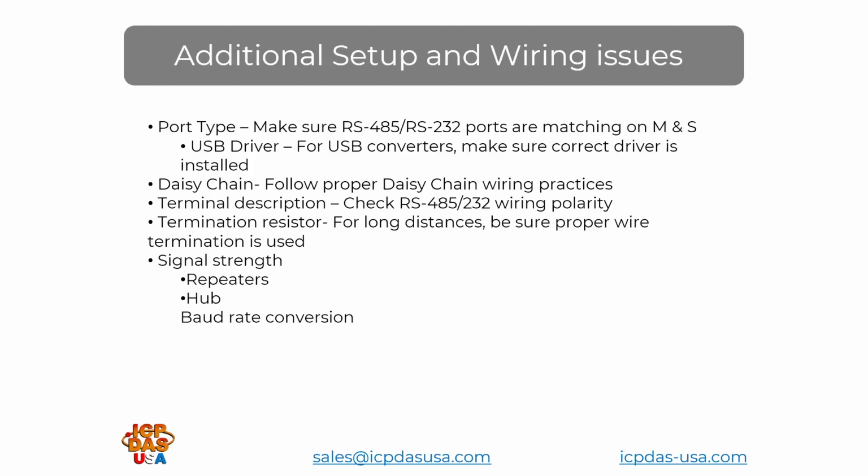Some of these issues here we have discussed prior. I just want to note some of these for additional troubleshooting. For port type, make sure you're wiring to the correct terminals. RS-232 and 485 ports are not the same, so they oftentimes have different wiring descriptions and terminal descriptions. When using a USB converter, make sure you use the proper driver supplied by the manufacturer.